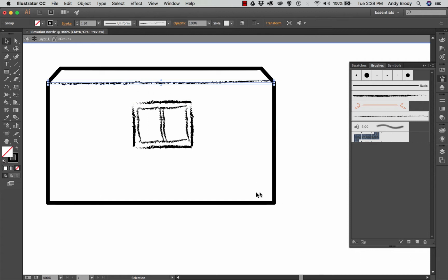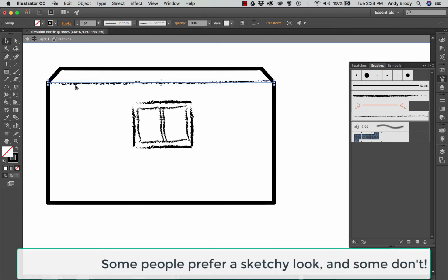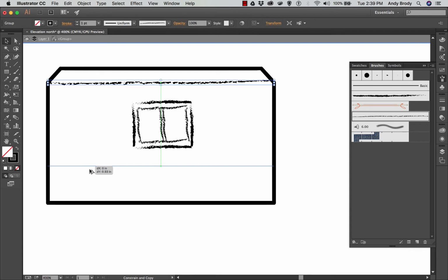Let's say I wanted a wall base. I can just use the select command, select that individual line, and then hold down Alt, and when I click and drag, it makes a copy. If I hold down Shift after clicking Alt, it will force it to be only on the orthogonal. This is kind of like the AutoCAD ortho mode.